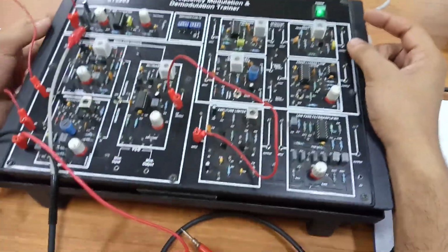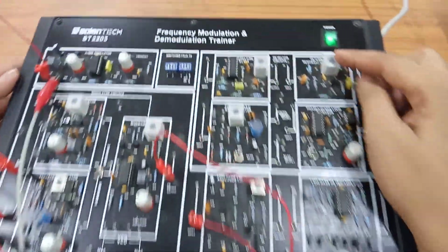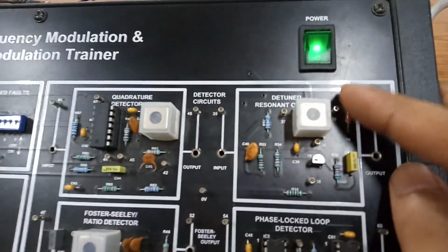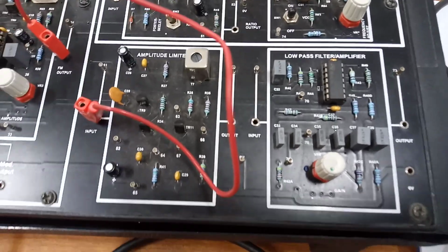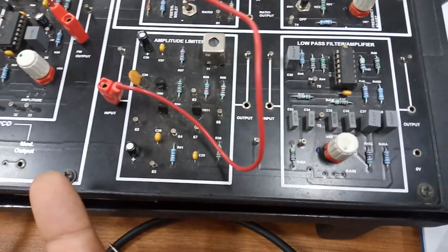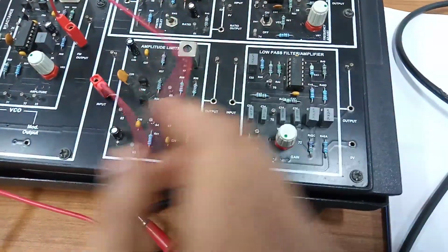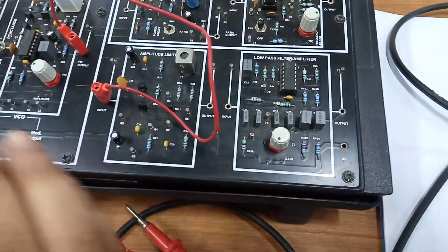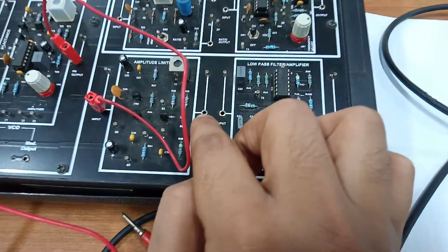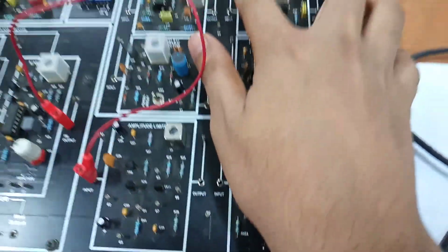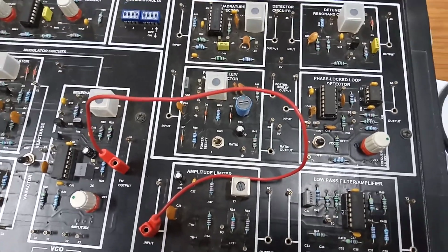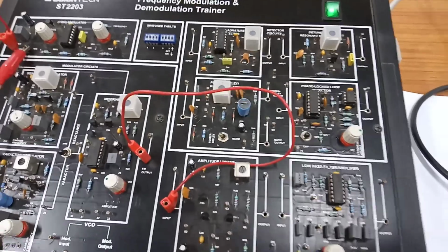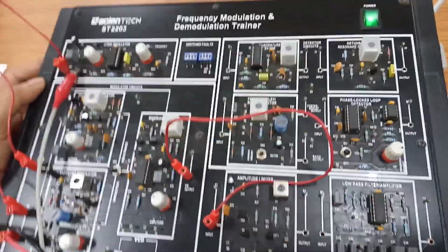After that, we detune it using the resonance circuit. You can see it is a detuned resonant circuit. We are going to give the output of this amplitude limiter to it, because first of all we are limiting the amplitude, removing the unwanted signals, clipping off the unwanted signals above the threshold level because noise might have been added. Here we don't need it, but we are using it so that we can remove any thermal noise that is going to come here. So I am going to connect the output of this amplitude limiter to the input of the detuned circuit. As I have told you, there is a frequency deviation of plus delta f in the frequency modulated wave. So there is a center frequency fc and a variation of plus delta f and minus delta f.